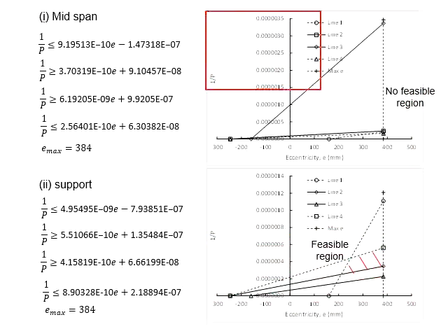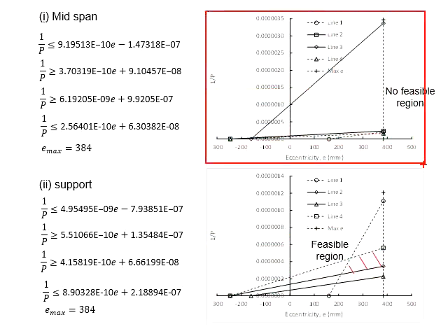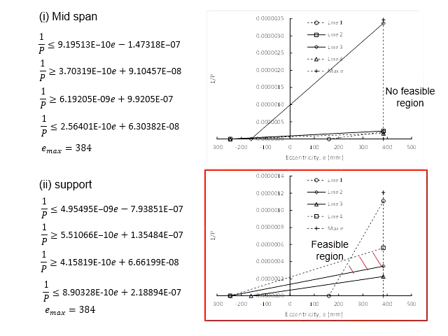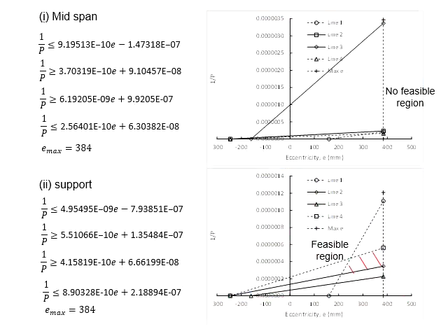The first diagram here shows the Magnel diagram for the midspan, and the second diagram here shows the Magnel diagram for the support. The solid line here represents it is greater, while the hidden line here refers to the regions which is less than.